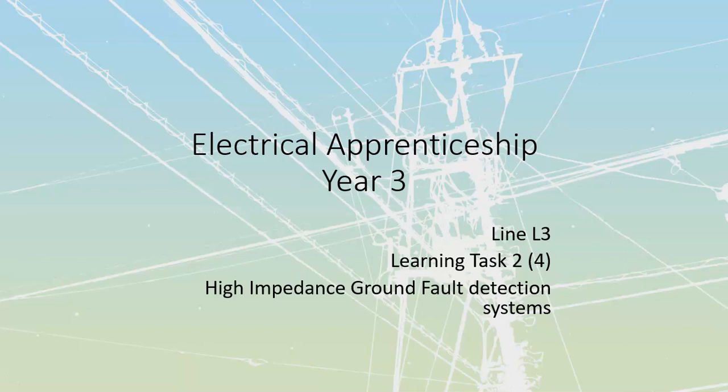Now, we talked about impedance grounding, what it actually is. The impedance is just a large resistance that's designed to give us only a tiny amount of fault current. We want to limit the total amount of fault current, which is going to limit the total AFI. Most of these are going to be done through resistive grounding devices or reactive grounding devices or zigzag transformers, but there are a couple of other systems that are also available.